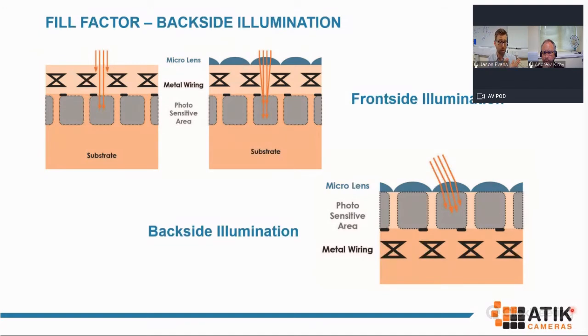In theory, the higher the value, the better the ability to distinguish variances from pixel to pixel. So if you've got an image with a lot of variance, a higher dynamic range is going to help you pick out those details, certainly in those faint images. Most of our cameras operate in either 12-bit or 16-bit modes, which gives you, let's say, 4,000 shades, or 65,000 shades for a 16-bit image.